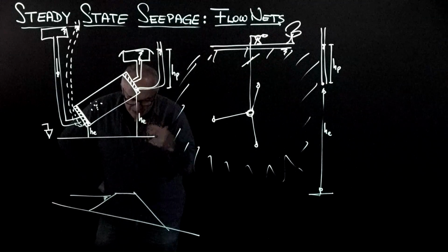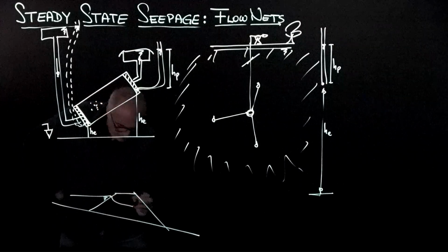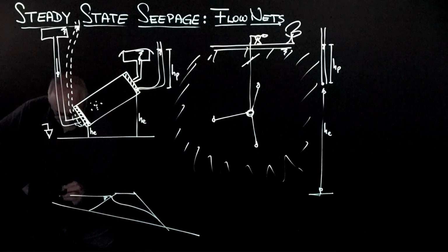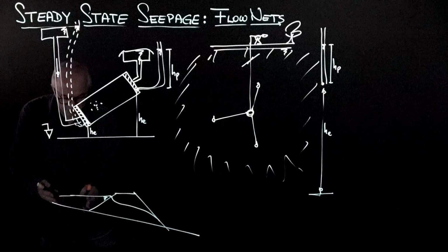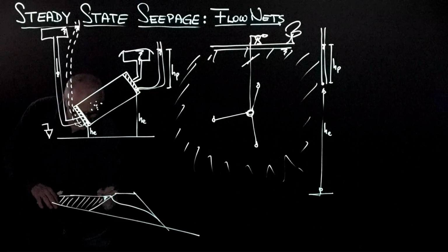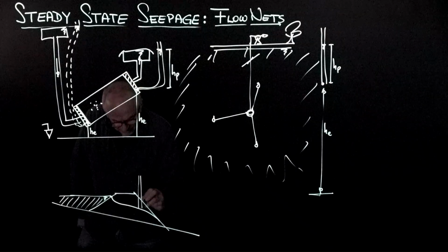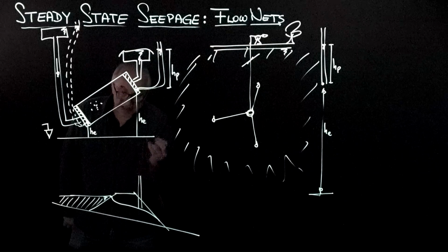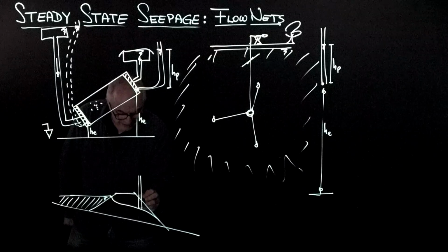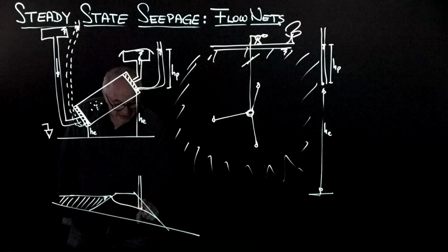So we can intuitively feel that the water will go in the dam, will migrate in the dam, and will create that surface. Now, inside the reservoir, like in any swimming pool, whether the bottom is flat or not, it doesn't matter. All this is an equipotential surface. Now, if I place a piezometer anywhere at the top of the phreatic line, it doesn't rise. That is it. So that means that at this point, the piezometric head on the phreatic surface is 0, and the total energy is controlled by the elevation.